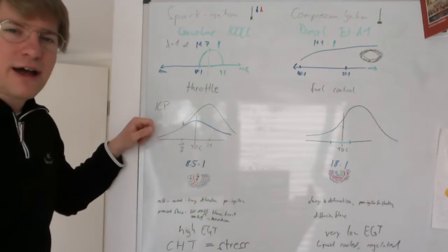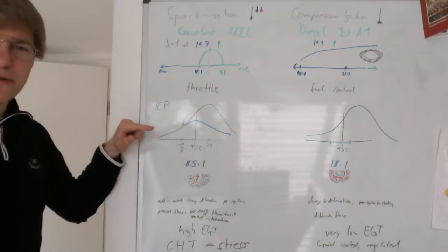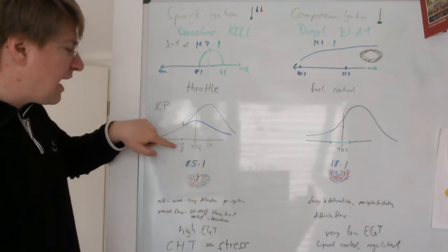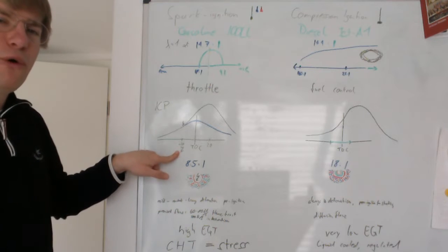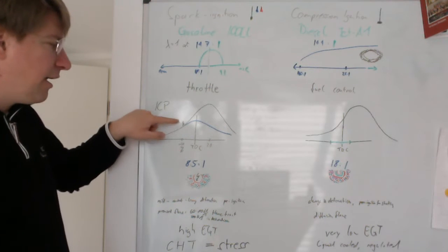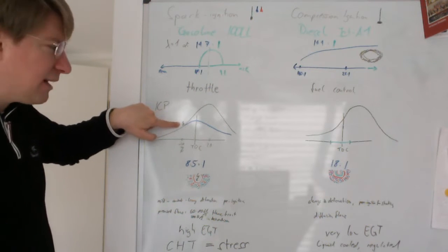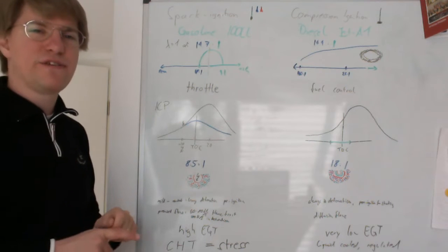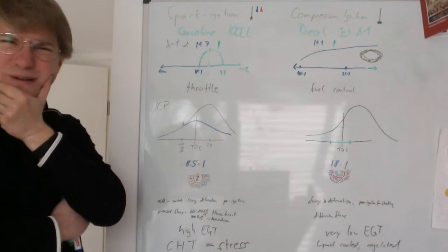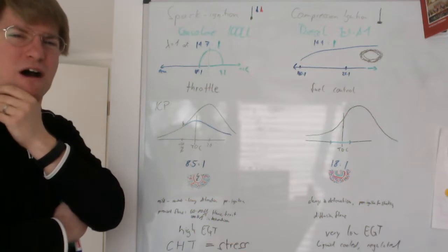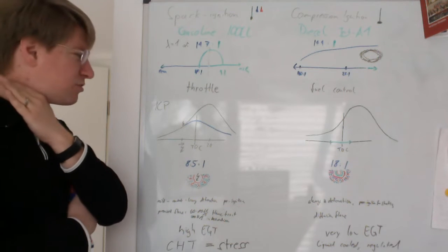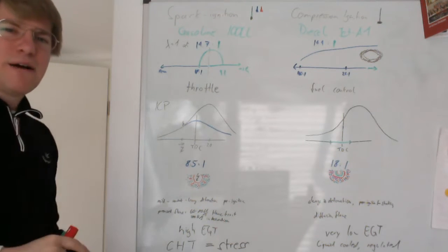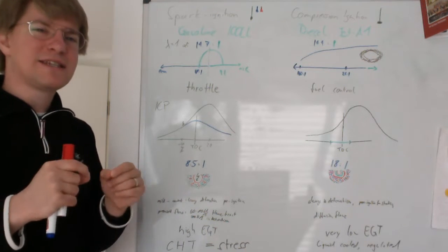But we are injecting fuel, so we are not running on air alone. And at about 20 degrees before top dead center, the spark plug fires and ignites the fuel-air mixture. Why do we do this before the piston is at the top? Doesn't that seem to be counterproductive? Well, what happens in the cylinder is not an instantaneous explosion.